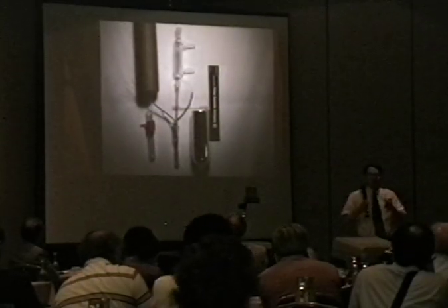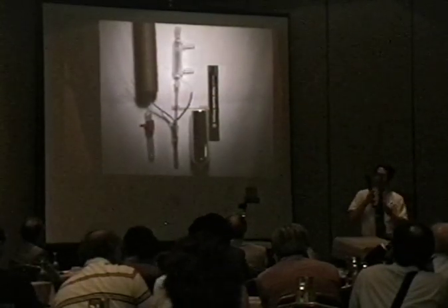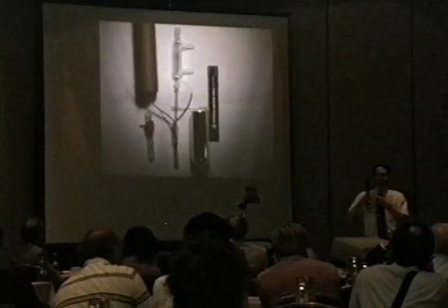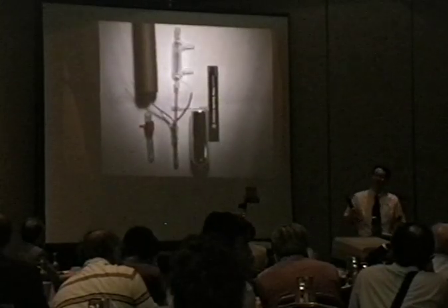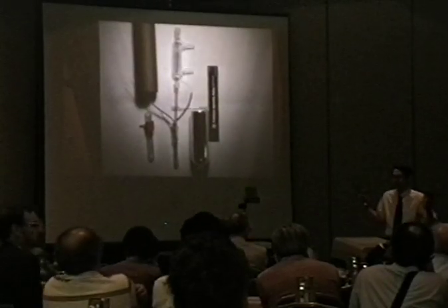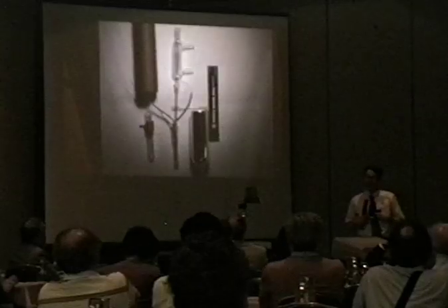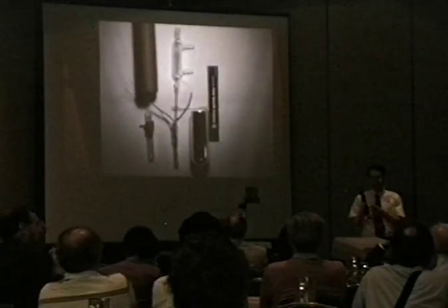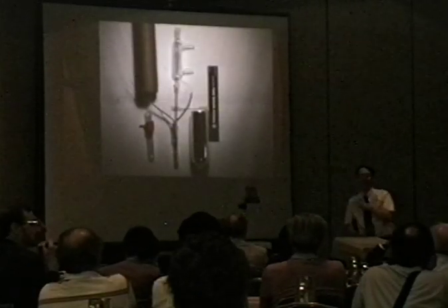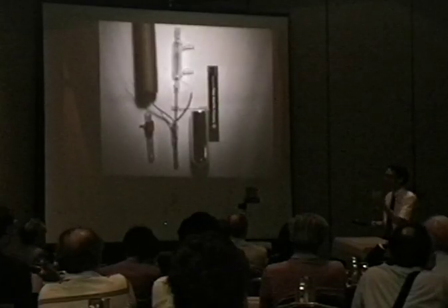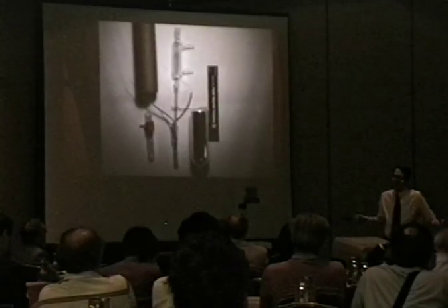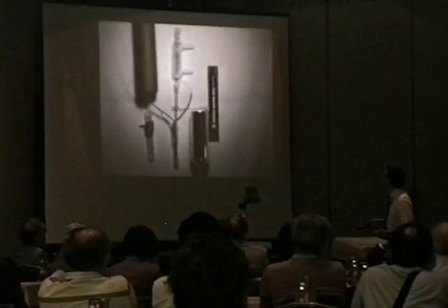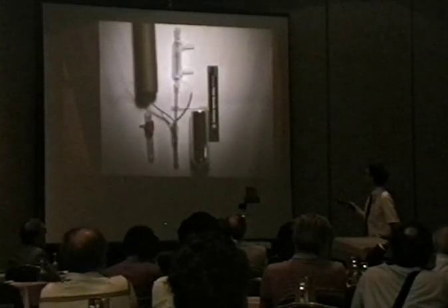Now that you've got a piece, you've loaded it, you've got a nice surface that doesn't have lots of pits and voids, and you've loaded it up to 0.65 or 0.7. The way I measure that is I just stop the current a little bit to see if it outgasses, and I know that I'm on the other side of the atmosphere. I do that visually because that's the only way I've got. I'm trying to go to higher temperatures.